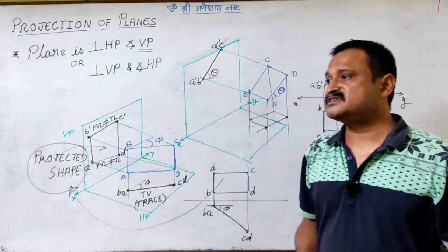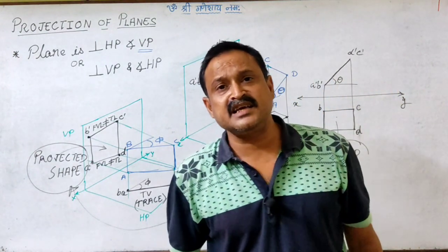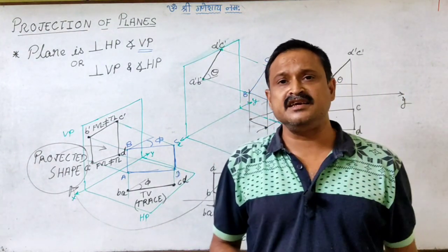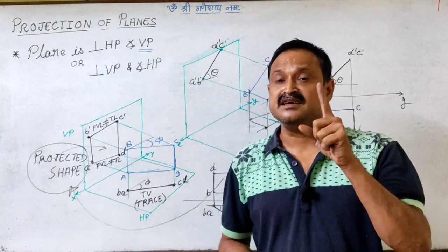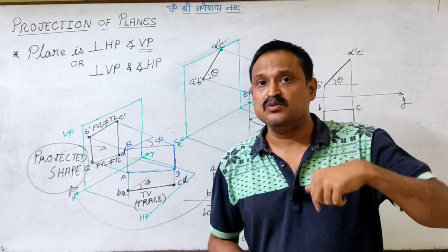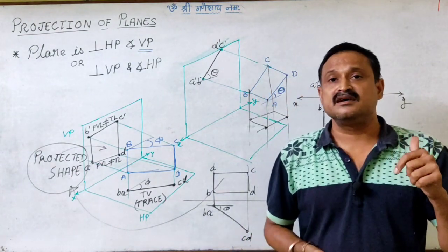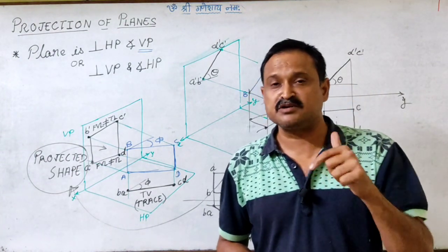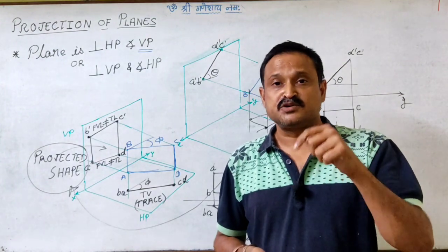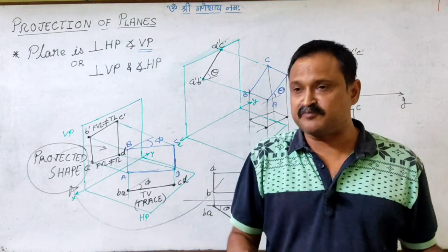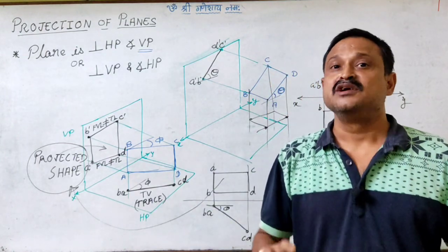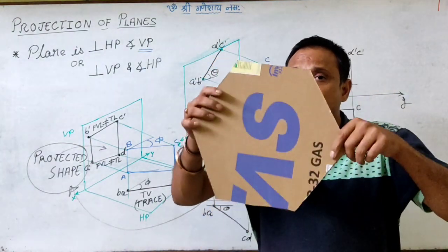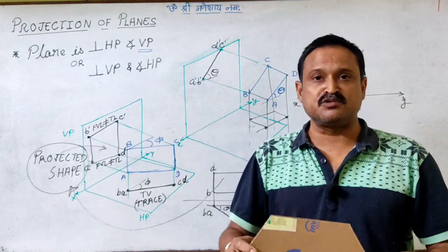Similarly, if it is said that the plate is inclined at phi to the VP, that means I have to give this inclination phi, which is visible in the top view, right? That means I must be seeing the trace, because I have to draw phi. So phi is to be drawn in the top view. That means I want the line image in the top view. That means I'll have to ensure that I make this plane perpendicular to HP.